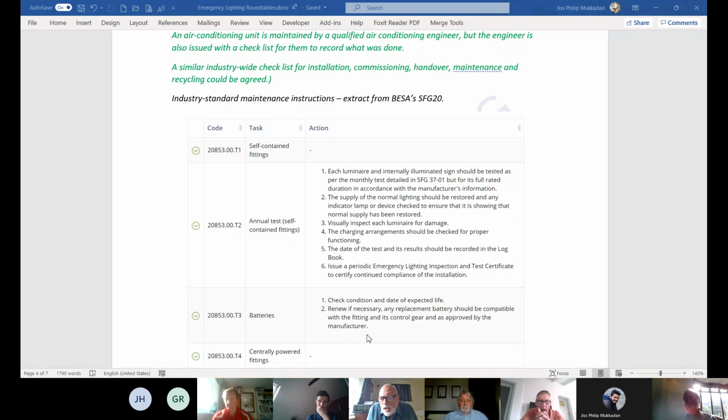So people who have the competence to install a mains luminaire have the competence to install an emergency luminaire. But the problem all the time is making sure it's done in accordance with the design engineer's work. And as Jim said, in the life of the system, that people don't replace it with a totally inadequate replacement product. So the positioning is so vitally important. A positioning of one foot in either direction just absolutely messes the system up completely.